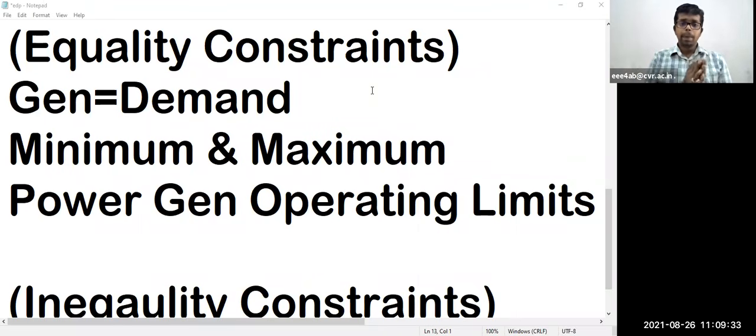I think in the lab experiment itself, you calculated the efficiency of the generator. So what is the efficiency you got? I think around 85%, some 88%. Someone is getting 90%, someone is getting 85, 82, like that. In the lab, that is a very old machine, so maintenance is somewhat less, whereas in a generating station, they always do the maintenance.